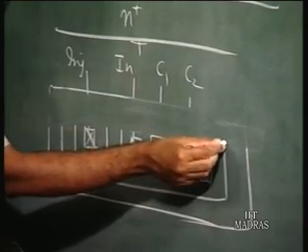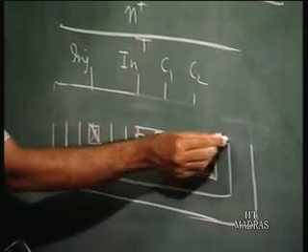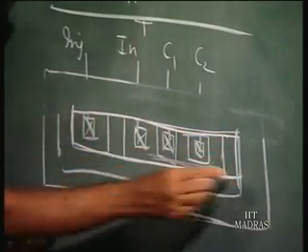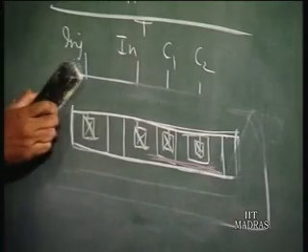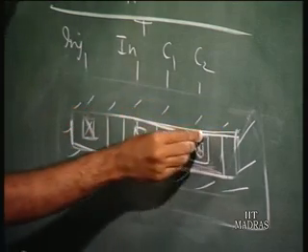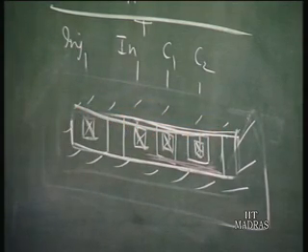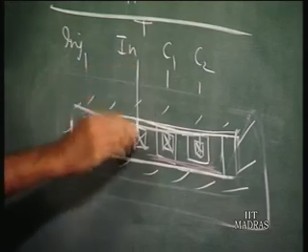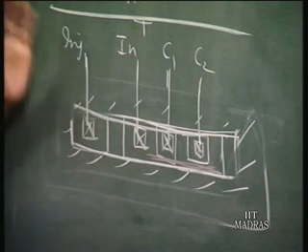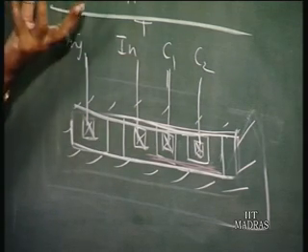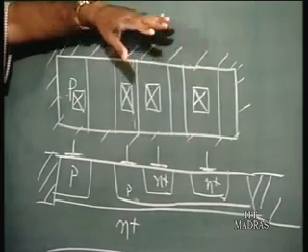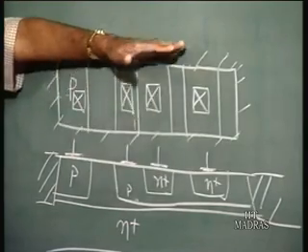All this region, this entire region, this collector diffusion, we have reduced the area up to here, and all around you have oxide. So we have removed a lot of this extrinsic area. These are the contacts. Is it clear? That is going to help in one way: a large portion of the extrinsic area has been removed. The rails on this side have been totally removed.